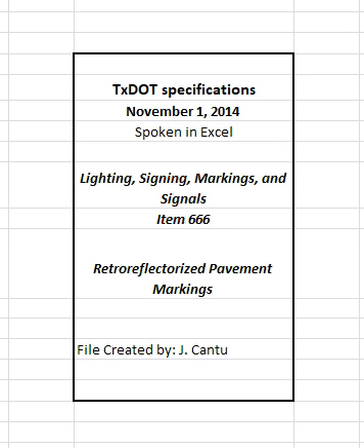3.2 Material placement requirements. Use equipment that can place at least 40,000 feet of 4 inch solid or broken non-profile markings per working day at the specified thickness, and at least 15,000 feet of solid or broken profile pavement markings per working day at the specified thickness.